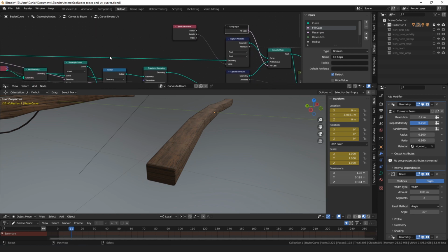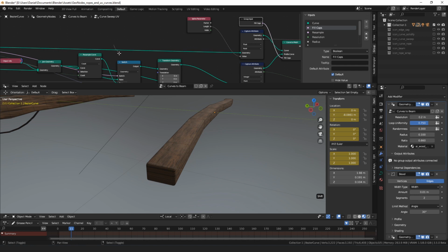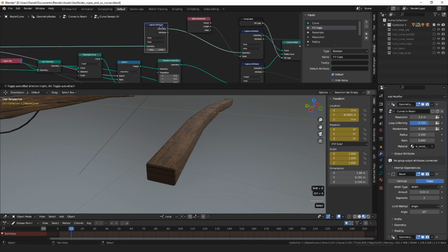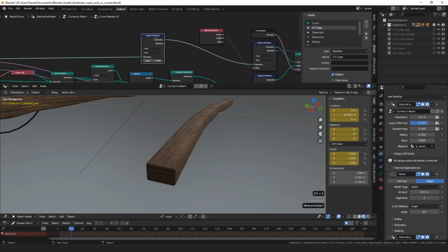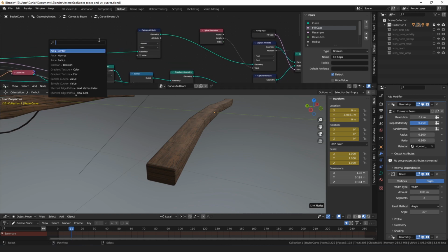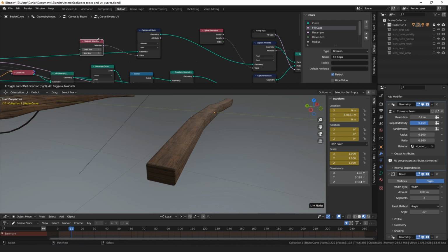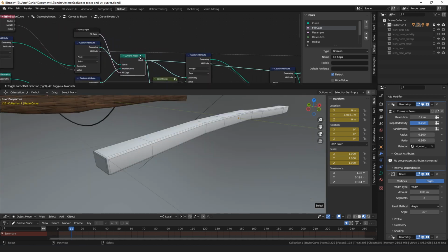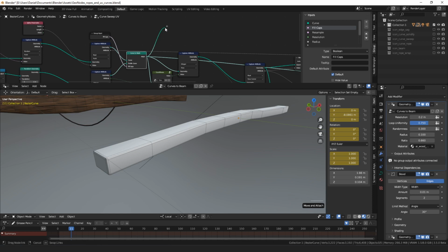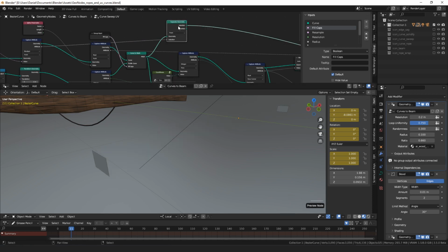So then if we do fill the caps, we need to unwrap them. So I think the way we can do that is we can capture another attribute on the input curve. We can do a Boolean endpoint. Then after we have made it a mesh, let's separate geometry endpoint.